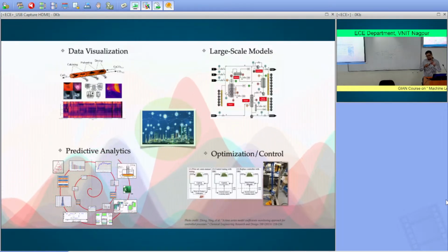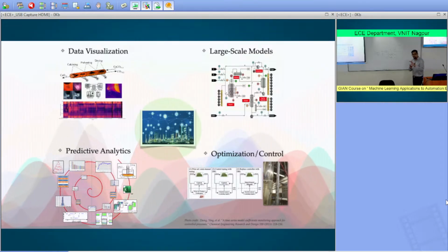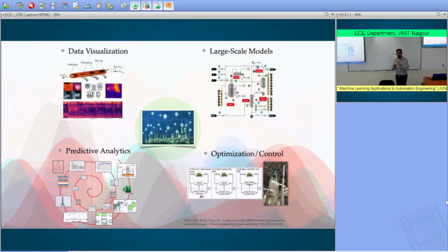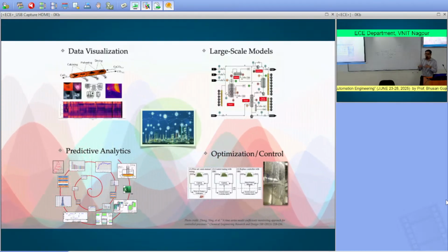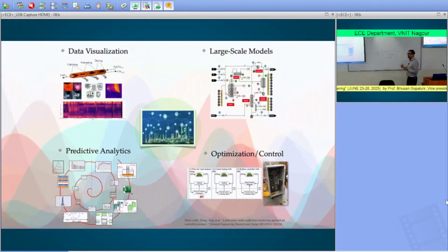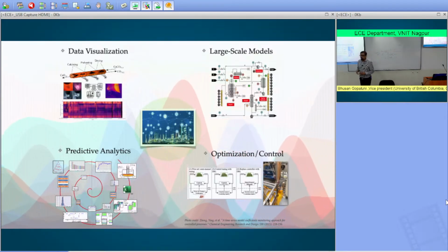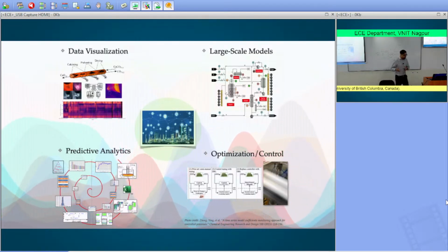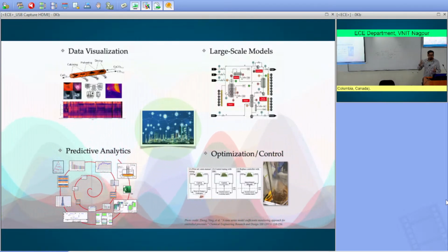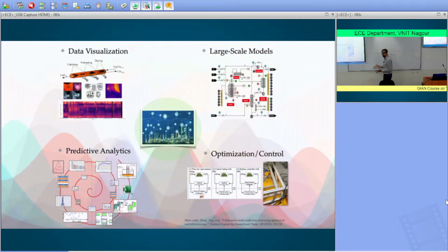So the problem is these electrodes, every once in a while, they lose the arc at the bottom of the electrode. Okay, so when you lose the arc, you're basically breaking the circuit, and the furnace shuts down. We don't know, nobody knows why that happens, but my hypothesis is the resistance of the ore changes depending on where it's coming from and what impurities are in the ore, right?